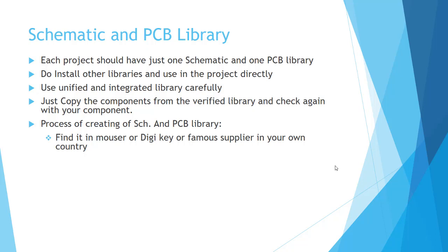Please do not use one component for all your resistors. For example, if you consider one component in your schematic library for the 1 kilo ohm resistors and another component in the schematic library for 10 ohm resistors, it causes that when you want to create a bill of material, you should manually edit it, and it causes many bugs.